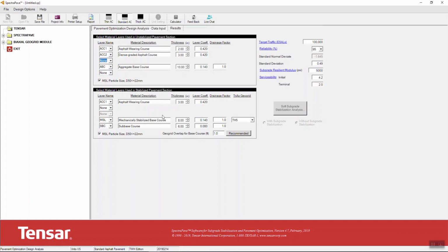Enter the pavement layers in the bottom box for the Tri-X GeoGrid stabilized pavement section. You'll also have the opportunity to make changes to the thickness on the results screen, so just take your best guess. You'll also need to select the specific Tri-X GeoGrid that will get incorporated into the pavement section. Each Tri-X GeoGrid provides a varying benefit to the section.